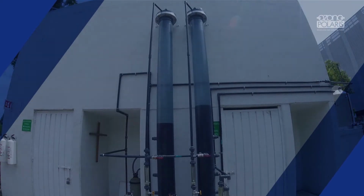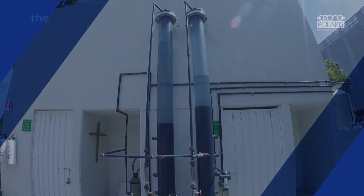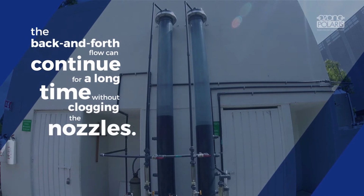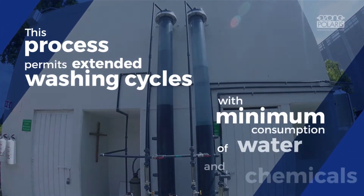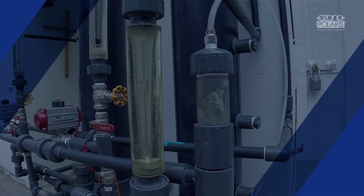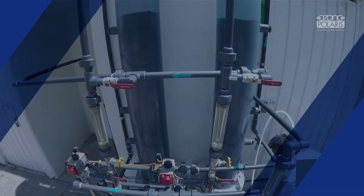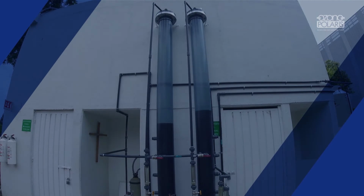As can be seen in this sped-up clip of two transparent 8-inch pilot filters, the back and forth flow can continue for a long time without clogging the nozzles. This process permits extended washing cycles with minimum consumption of water and chemicals, and just a small volume of wash water to be treated. It allows us to keep the effluent water quality within strict limits and prolongs the life of the carbon from months to years.